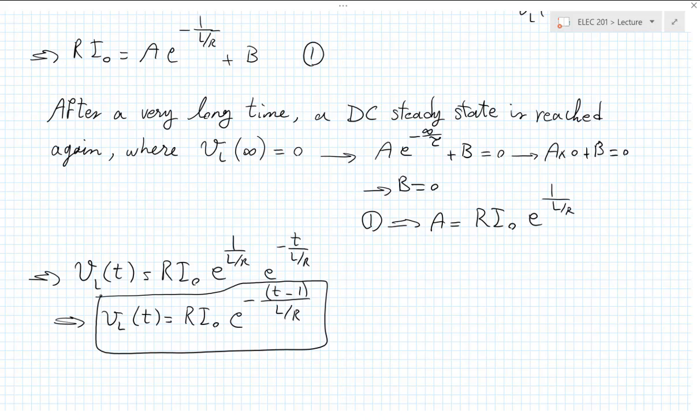So here's just an example to show you another step response, to point out a few things. First of all, you didn't need to have the source itself changing. I achieved this step behavior by using a switch separate to the source, right? An external switch. But I still made sure that my circuit didn't have any no-nos, such as a current source connected nowhere.